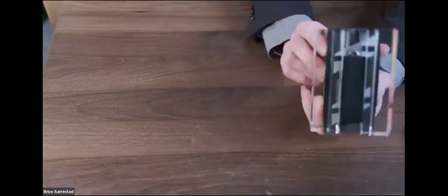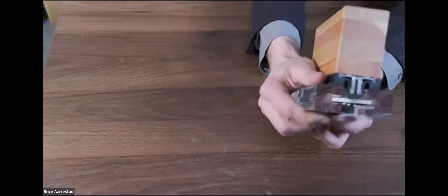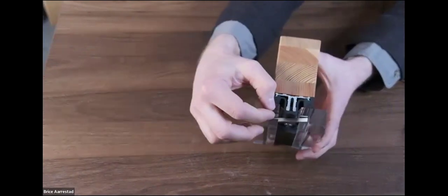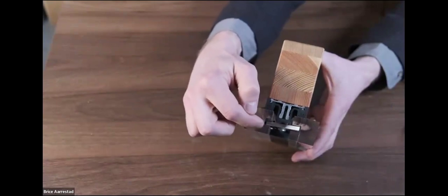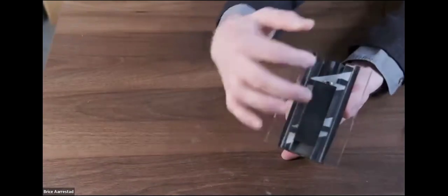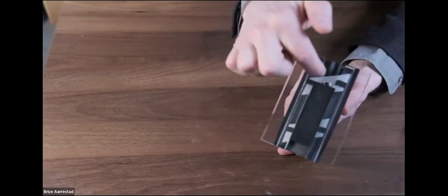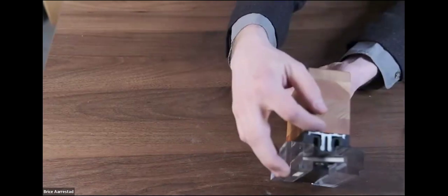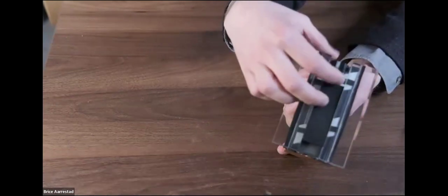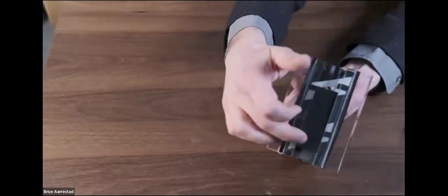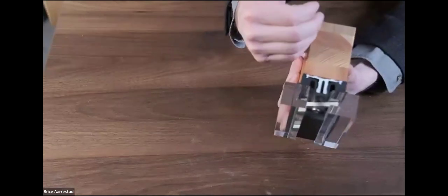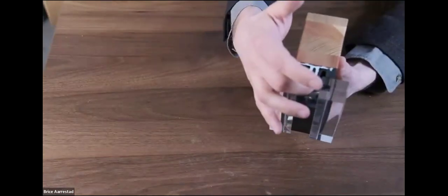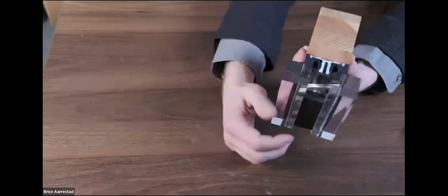It uses what's called a toggle system. So in the spacers of the IGU, there is a toggle, a channel that's put into that spacer, and then these toggle clips are rotated to grab that channel and then mechanically attached into the base profile. So it's a hybrid system. Then it's finished off with a rain screen sealant on the perimeter. So it's a hybrid system between a mechanical system and an adhered system. It's mechanically attached, but it's silicone finished.